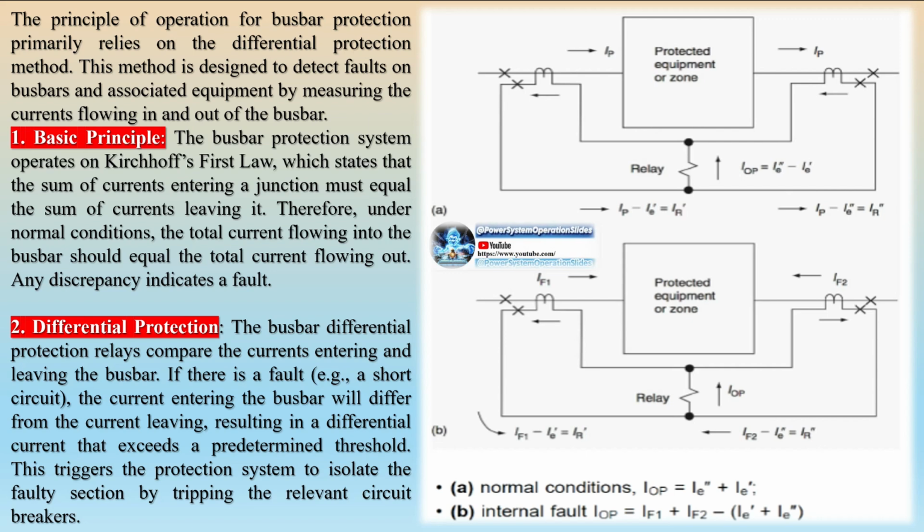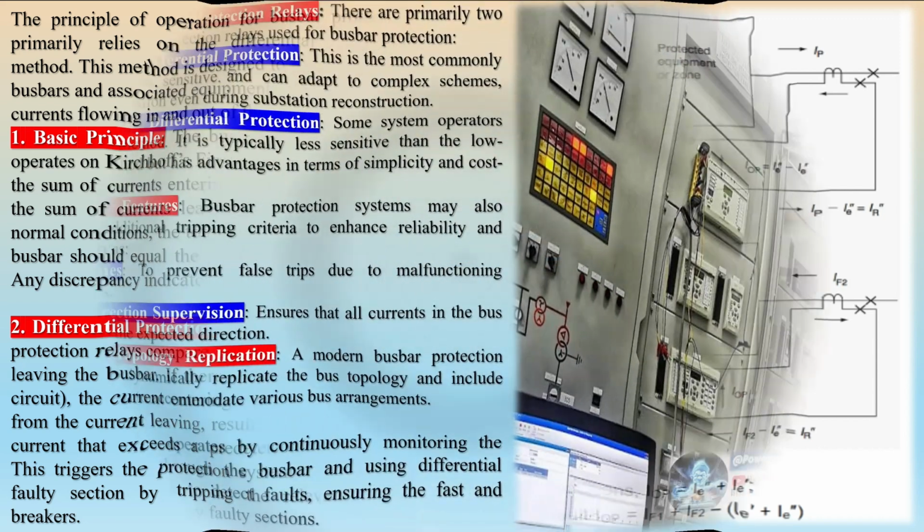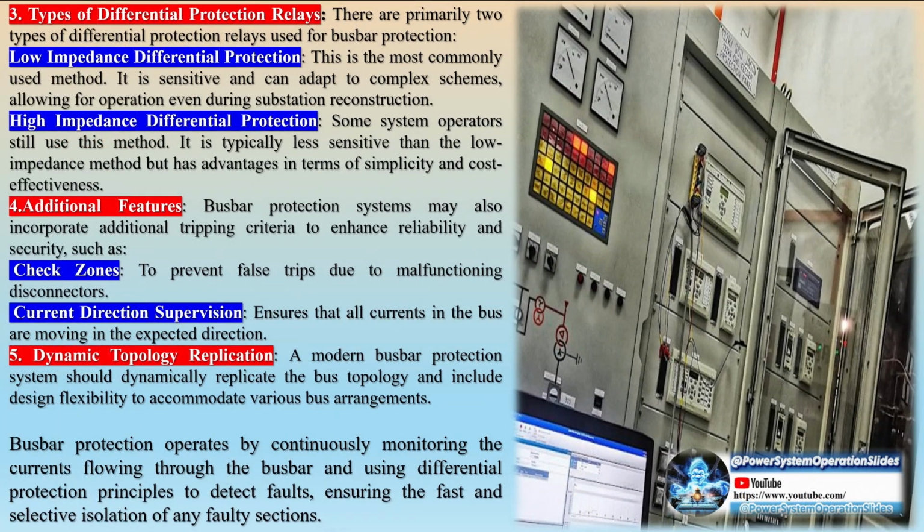Decentralized arrangement: historically, before the advent of numerical decentralized busbar protections, they were centrally constructed. All process data, including CT currents, isolator positions, and tripping channels, had to be wired back to the central busbar protection panel. Significant interconnections, such as those for starting circuit breaker failure protection and blocking auto reclosure, were required between protection panels. These conventional arrangements involved extensive cabling, making engineering, commissioning, and maintenance time consuming and costly.